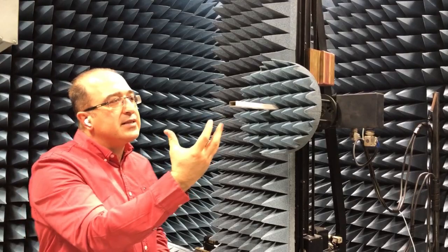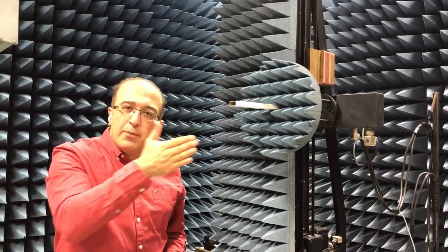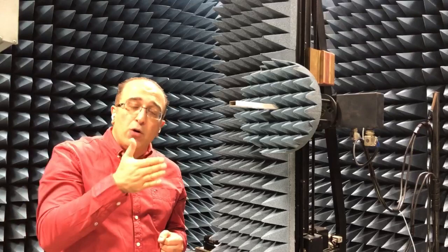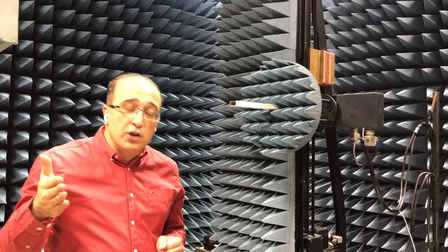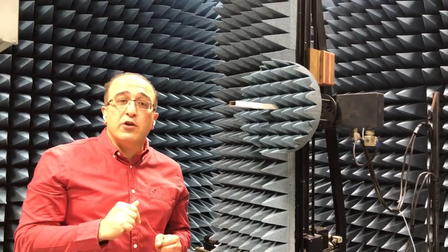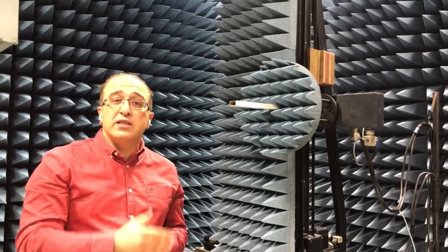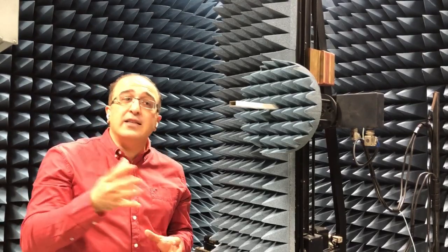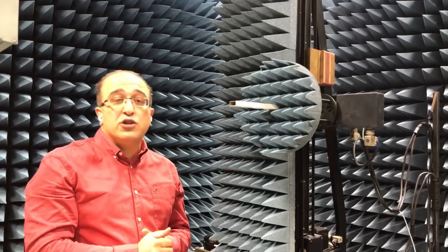And so this is a waveguide that we have, and this waveguide works above a certain frequency. So for example, you may think of it as a high pass filter. Below a certain frequency, it does not guide. After a certain frequency, which we call cutoff frequency, it guides. And when it guides, there are different modes. So that means different field distributions within the waveguide.